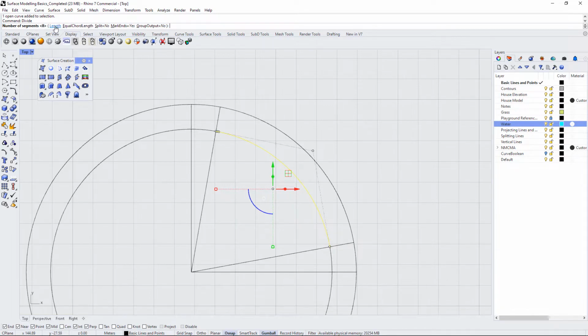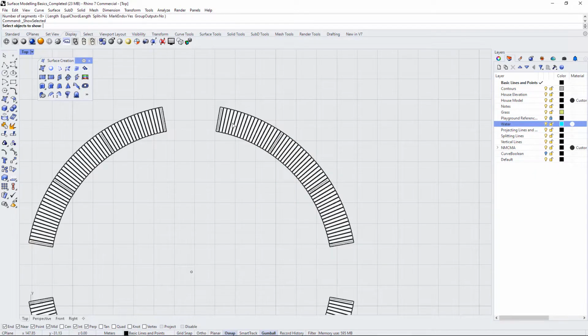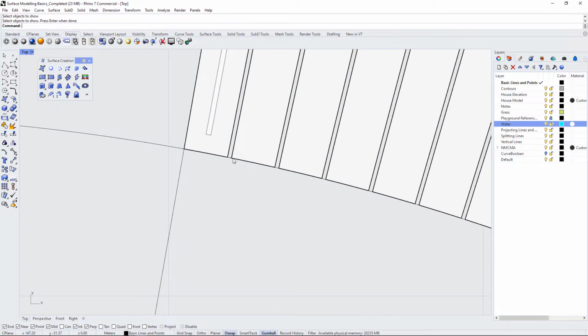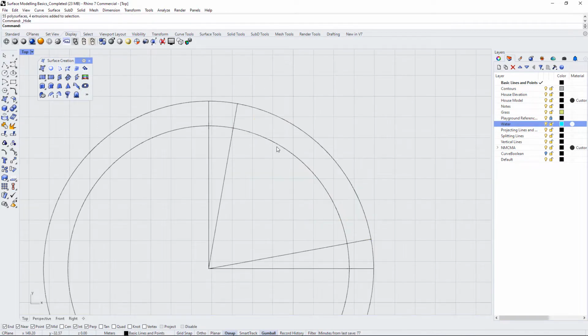So you can choose a length of segment, or you can choose a number of segments. And we know our length of the segment was 14 centimeters, but I'm just going to unhide that and see what the total is with this gap as well. So with the gap, it's 0.15 meters. So I can do a few things. I can divide this using the divide command into lengths that are 0.15. And you see it puts a point along this entire curve to denote where 0.15 is.